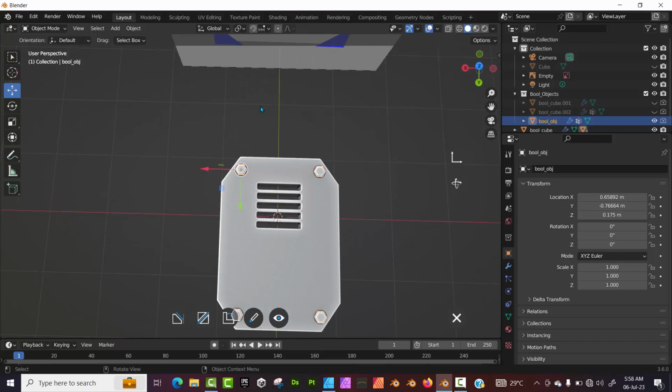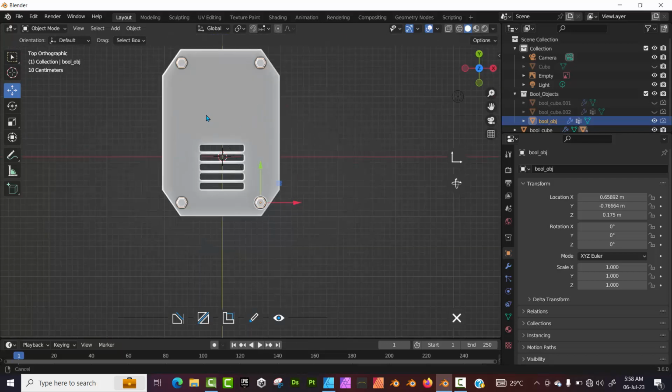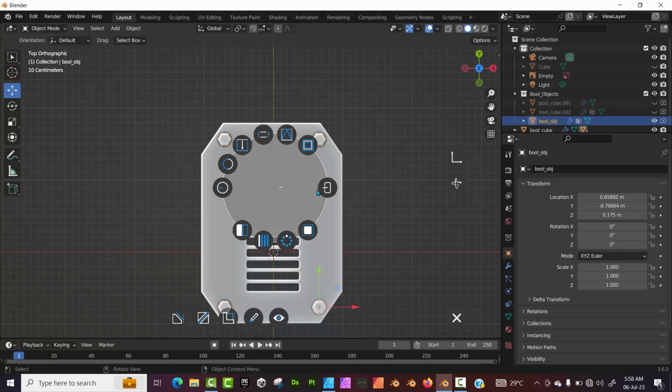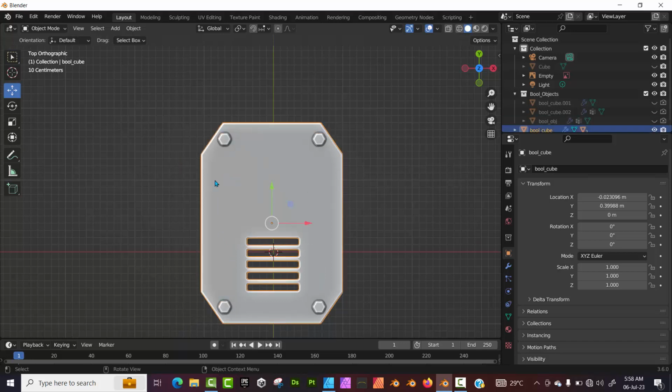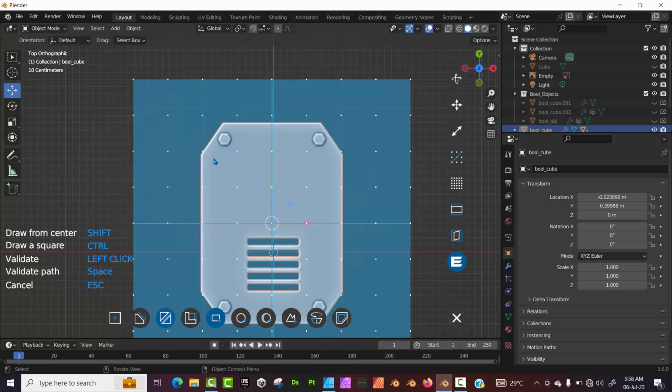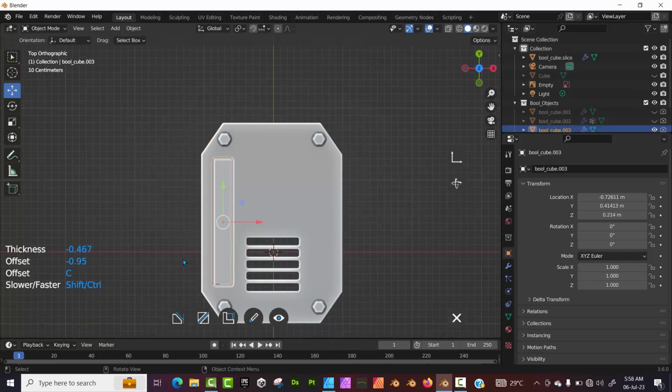So now that we have this, we can always add any other additional details. We can even use a slice right here at the top and then add some slices at the section. Then we can call this quit, or else we're just going to keep going. So let's quickly do that. So let's click on the object, press F, and let's go to slice, right click, and let's just draw a nice, slicey shape like so.